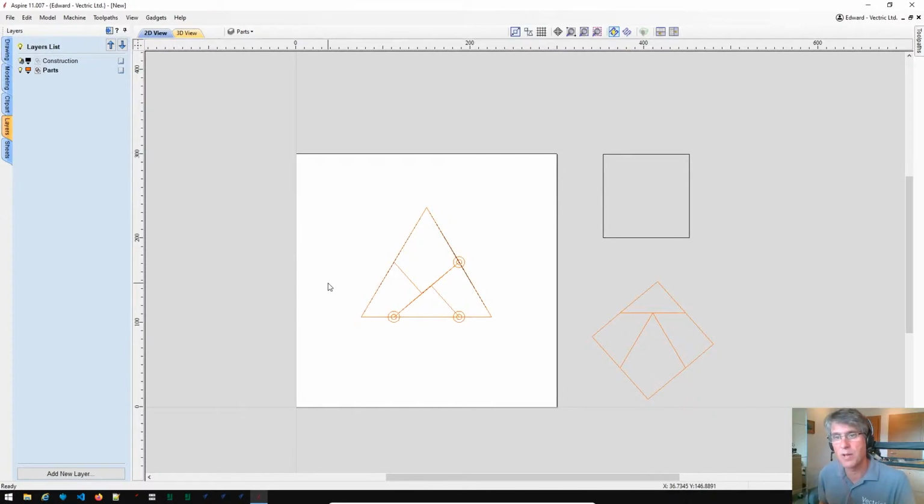So I'm going to cut these parts out of a piece of scrap wood, nice wood though. I've got a nice bit of door frame that's oak, so I'm going to use an oak panel. I'm going to halve this first, so that's about 420 mil in half, and this is about 150 mil, and the whole thing is 20 mil thick. So that's what we're going to use. And so now I can start to think about the manufacturing space.